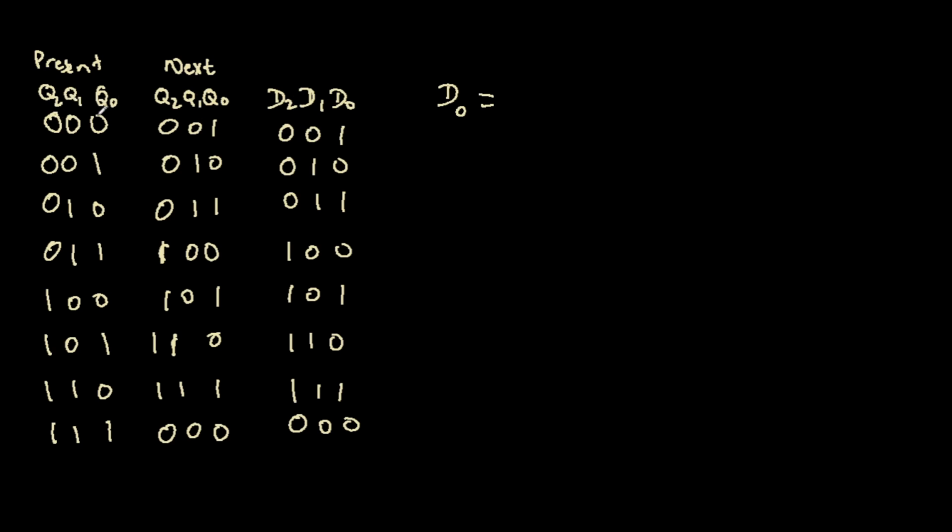So the way we're looking at this truth table is, what is the logic combination we can use of these outputs that will result in this particular input? If we can have a logic combination of these outputs that results in this set of inputs, then whenever we're in this state, it will definitely go to this next state, because that logic combination of this particular set of values will cause the flip-flop to move to this particular next state.